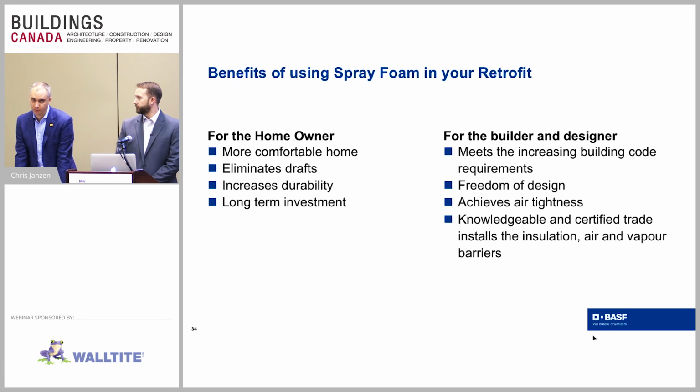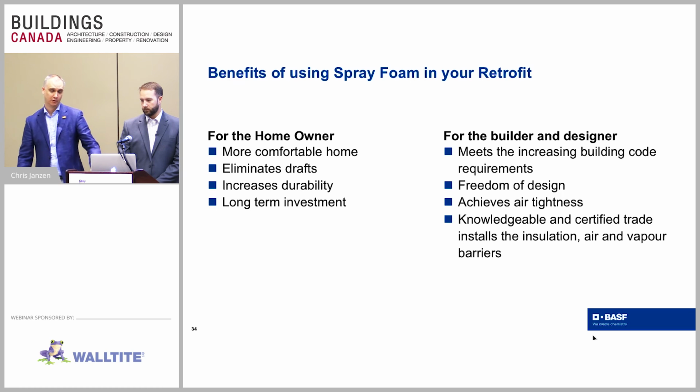The product's been used for over 40 years. We've had lots of durability testing, flexing the walls to see if there's any cracking, before even doing the air leakage testing. That's part of the 742 requirements: is this product durable? The walls actually shift during this testing, so there is movement involved.